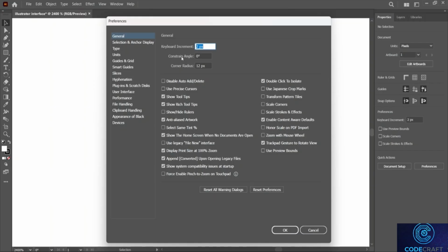They are horizontal and vertical by default. Enter another degree into one of these text fields to rotate the axis. A positive number moves the rotation angle counterclockwise, and a negative number moves it in the normal clockwise motion. So always remember, a positive number equals counterclockwise and a negative number equals clockwise.